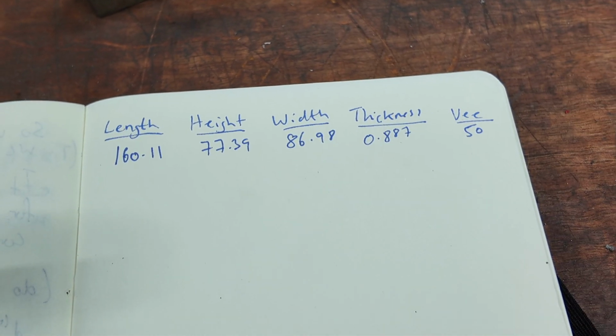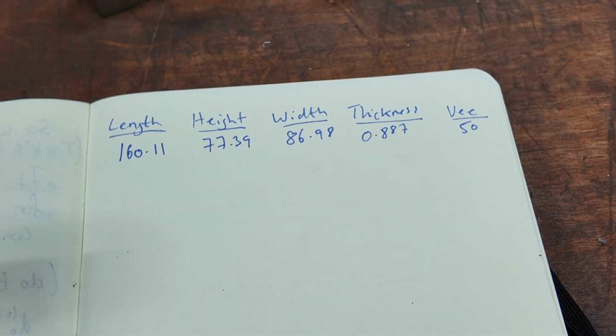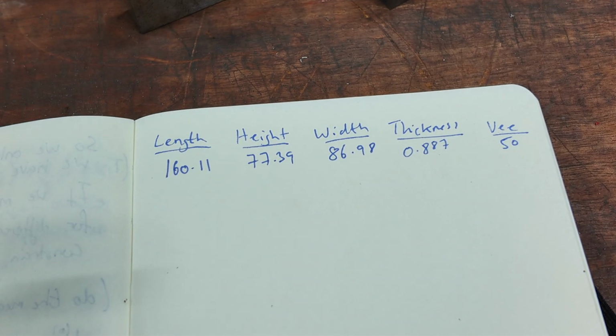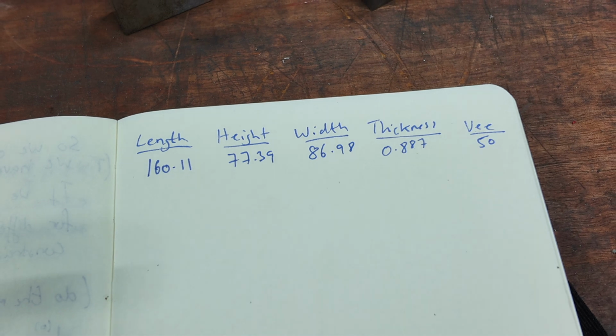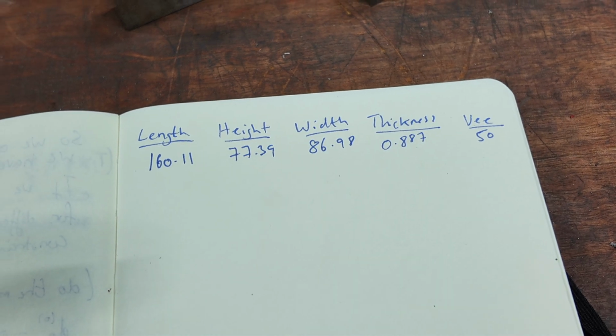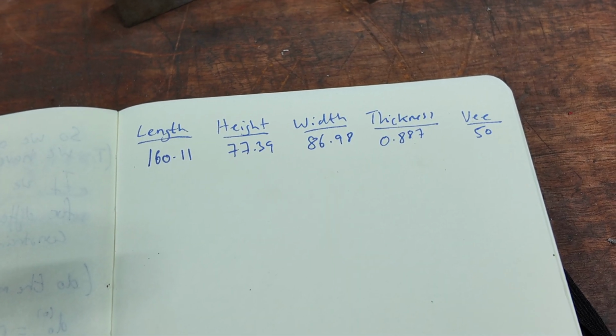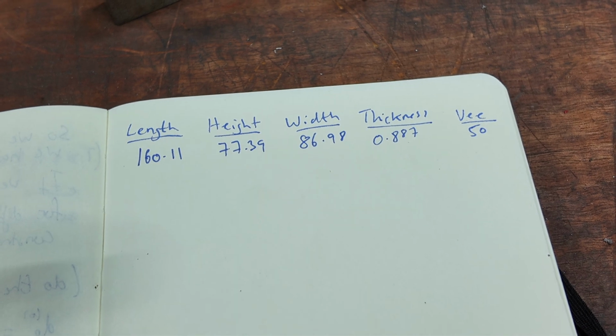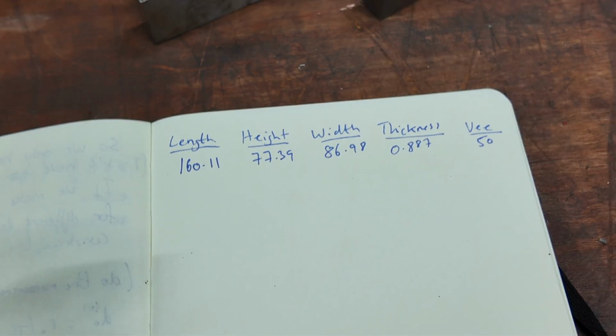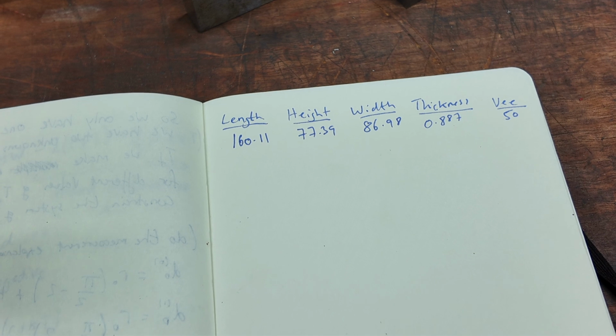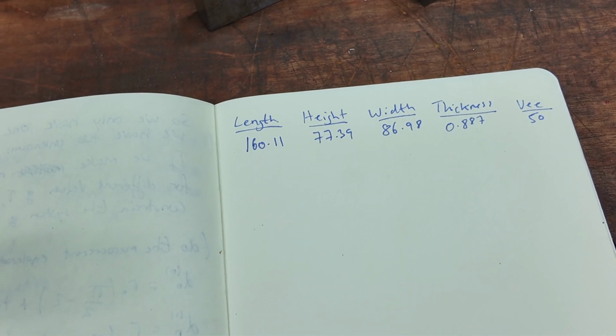So we've just got to do that again with 2 millimeters or nominal 2 millimeter thickness on this 50 mm V, and then for each thickness that I'm going to test, just for now just 1 and 2, on the other 3 V sizes as well. So magically we shall bend some metal and the table shall be full.